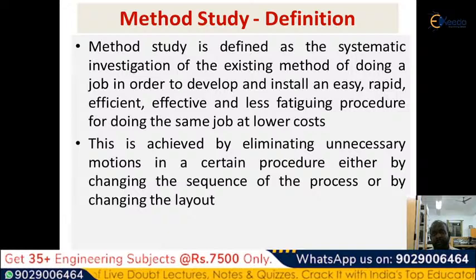So method study mostly concentrates on how to eliminate these unnecessary motions. Say you have 10 machines. A product need not go through all 10 machines. Sometimes only 5 machines can be used, sometimes only 3. So how you can utilize the other 7 machines, that also we have to see. Also, if these machines are placed at different locations, what will be the travel time between each machine? I have to keep that in mind. If there is any possibility to reduce this timing, I have to do it. So method study is going to eliminate the unnecessary motion of a particular product inside the industry. That's the main objective.